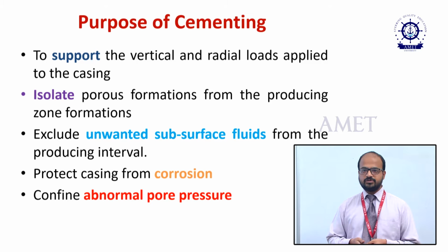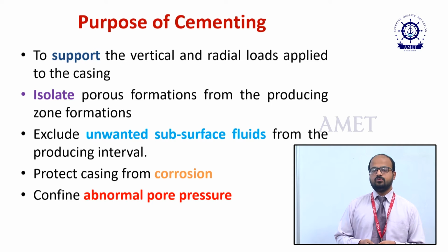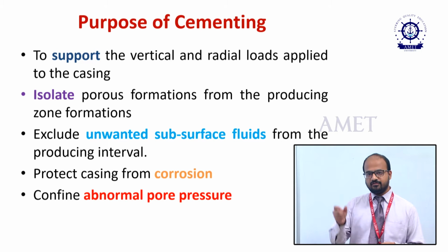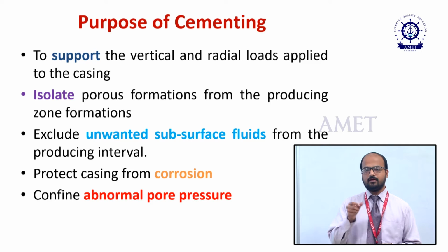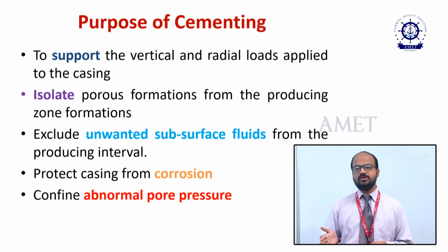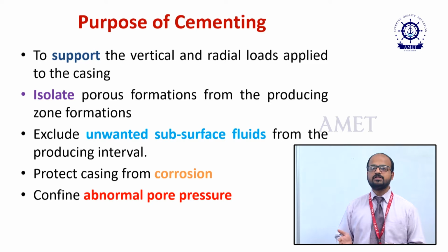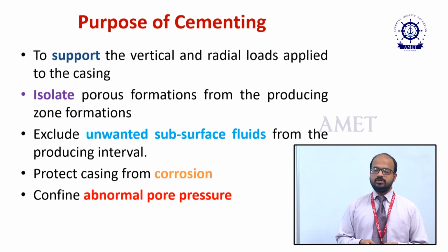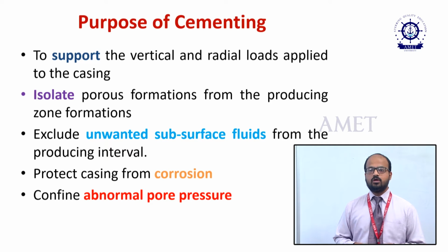For that I have to preserve the well. What do I have to do? I have to fill the annular space with cement again. If I do that, then what happens? A seal will be created between the formation as well as the casing. Now your well becomes stronger.